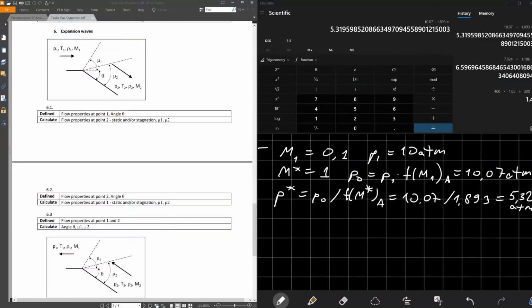Okay, but for some people it becomes a confusion when I draw a vector in one direction and ask to calculate the flow properties, and then I draw the vector in the opposite direction and ask to calculate the flow properties, and people start to have problems because they don't know that it doesn't matter which is the flow direction. Since it's reversible, you can always put it in any forward or backward direction, no matter. The flow structure will be absolutely the same, so do not forget this on your exam, and for your future it would also be important.